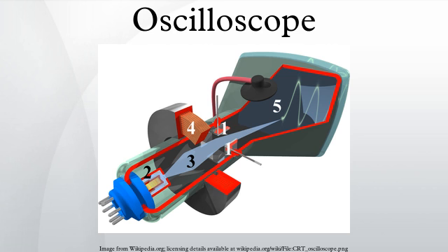As well, its time domain response has to represent transients accurately: minimal overshoot, rounding, and tilt of a flat pulse top. A vertical input goes to a frequency-compensated step attenuator to reduce large signals to prevent overload. The attenuator feeds a low-level stage, which in turn feeds gain stages. Following are more gain stages, up to the final output stage which develops a large signal swing for CRT electrostatic deflection.